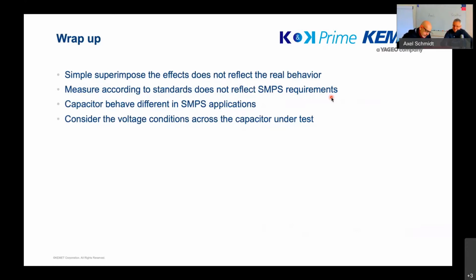So getting back to the beginning, we need to do some more investigation. Again, the approach is that you have a cost optimized design. That means you don't use more of these MLCCs. And I see a lot of designs where people more or less spread out MLCCs just to be sure they have enough capacitance. When you deal with automotive customers, they typically count the tenths of a cent, so it really makes a difference if I use 1 or 3 4.7 microfarad capacitors. What we want to do is get closer to the real behavior, which allows the customer to not over design their application and use only the number of components they really need, and not some safety margin, which probably increases the cost of the overall application.